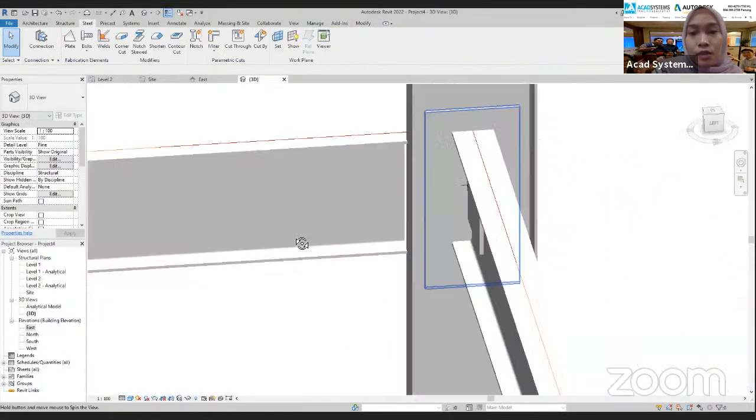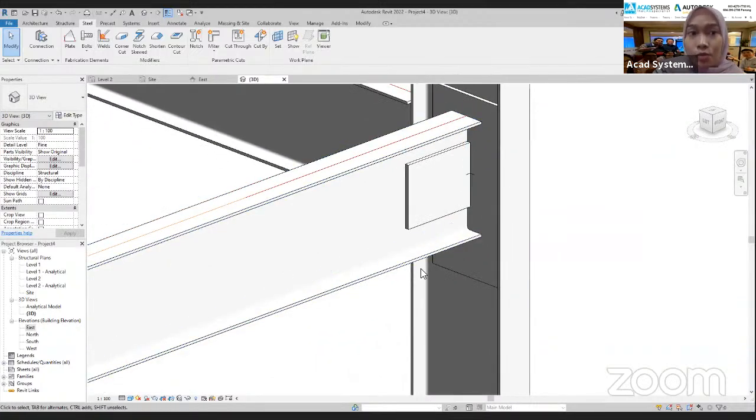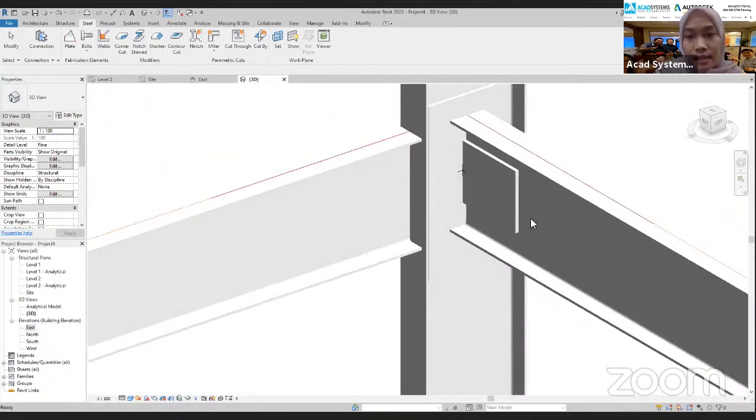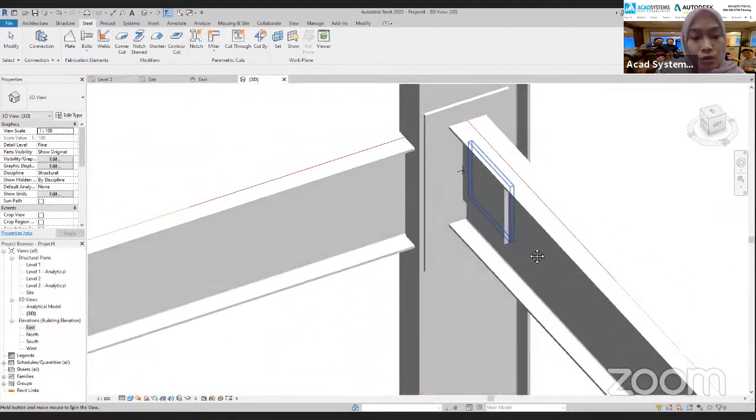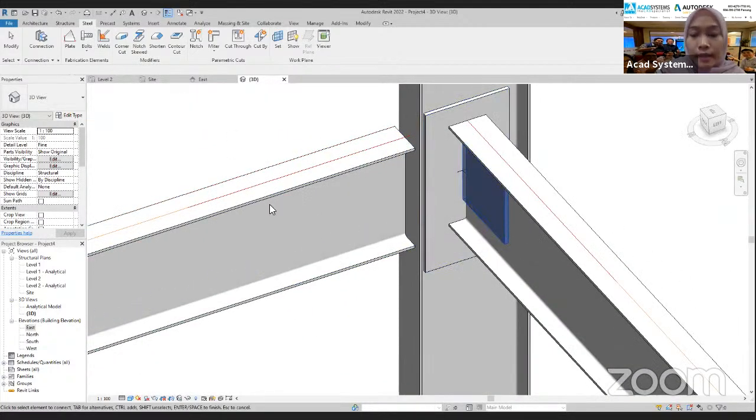So after we're done with the welding part, let's add the bolts on our elements here. So up here still we have the bolts. So just click on the bolts, click here, and so the first thing you need to do is choose from where to where the bolt will go, the initial part of the bolt and the end part of the bolt. So the bolt will start from here and end on this plate. Okay, again, click here, control, and click also here, and then enter.